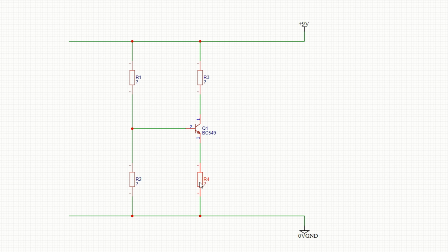Say you've got a 100 ohm emitter resistor and a 1000 ohm collector resistor. For any given current within the possible range, the voltage across the collector resistor is going to be 10 times the voltage on the emitter resistor. And seeing the emitter resistor voltage is going to track in kind of emitter follower mode from the base, as long as it stays in a linear range, you have a 10 times gain amplifier. E.g. 1 mA through that is going to create 100 millivolts at 1 mA on 100 ohms, and 1 volt at 1 mA on 1000 ohms.